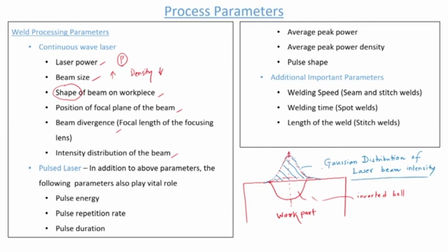So, the consideration of Gaussian distribution is very much essential when we use numerical analysis to compute the temperatures during laser welding operation. So, what kind of laser beam intensity profile is to be considered? Most of the people do consider the Gaussian distribution. Some of the people are considering uniform distribution.